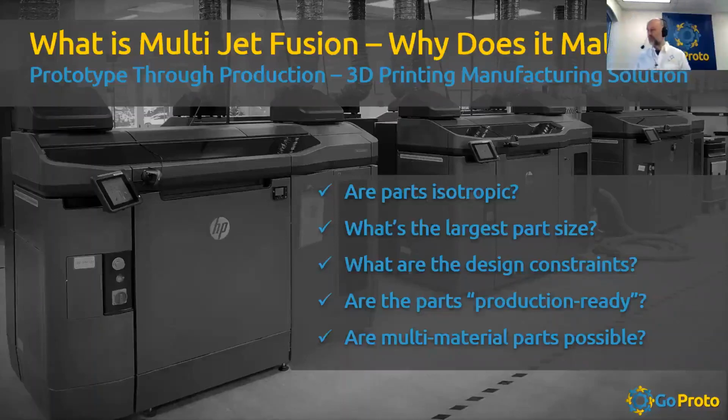What's the largest part size? The build size for multi-jet fusion is 11.2 inches by 14.2 inches in the X and Y. So 11.2 by 14.2 by 11.2 tall. So fairly large parts, not as big as some of the other technologies like FDM. SLS can make larger parts. So building in sections and being able to fabricate together if they get bigger than that is important. And the TPA is bondable. It is something that we can print in sections and fabricate together.